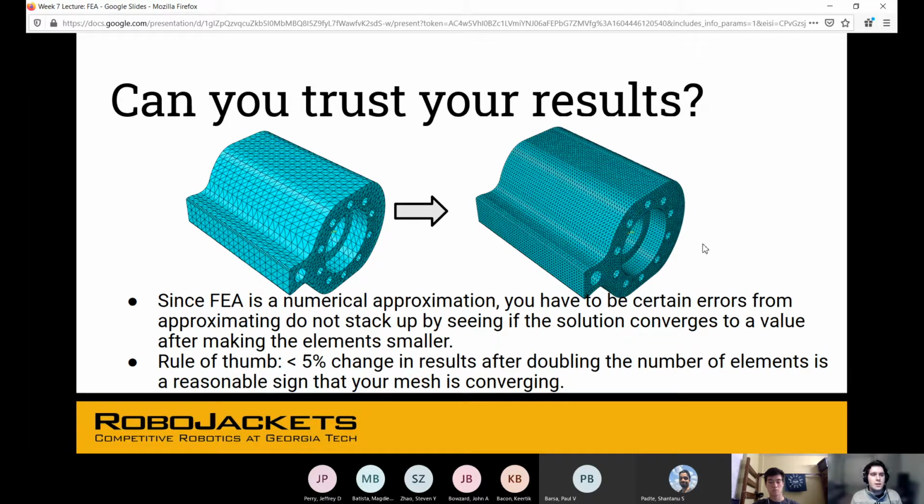And what I mean by this is, you can think of this like, let's say I have a circle, right? So this is a glass with just quadratic elements. You can imagine trying to fit squares to the entire geometry of this circle over here. It's going to be like an n-sided polygon, right? You can think of it like that. So unfortunately, because the geometry isn't exactly what the mesh is telling it, it's going to have errors from that, as well as from anything that's ignoring higher order interactions, but we don't have to get into that.